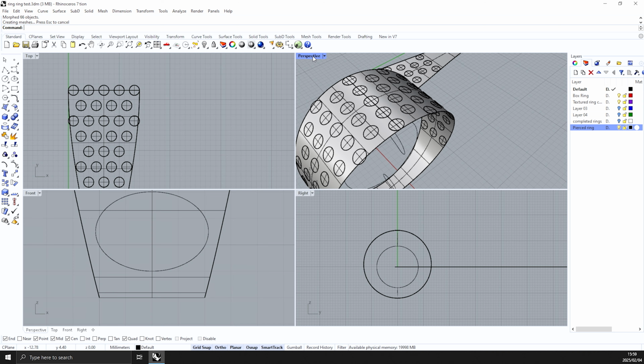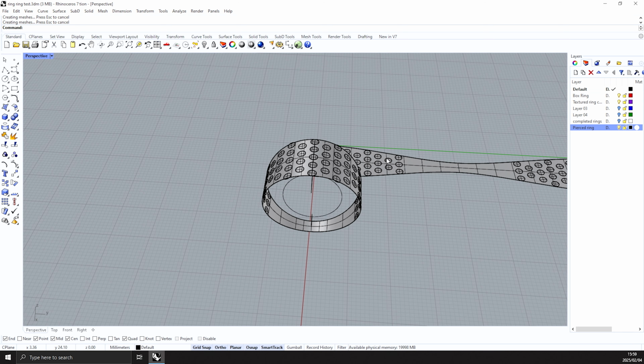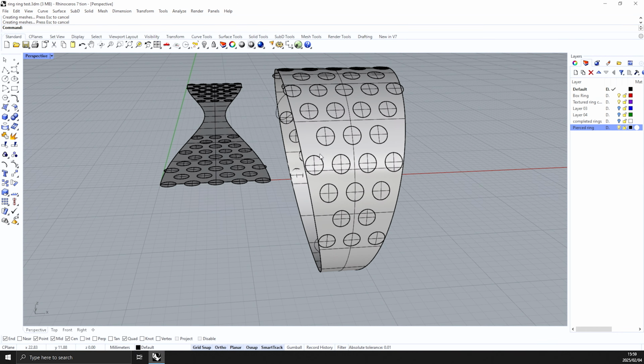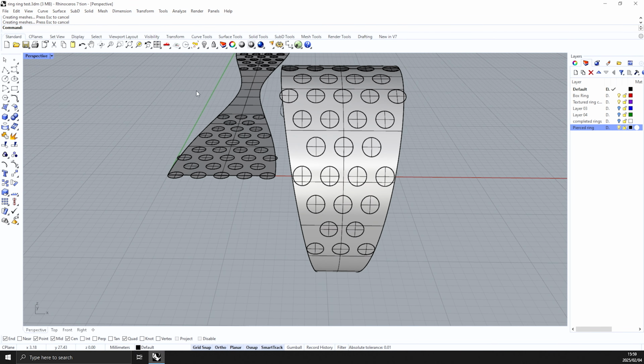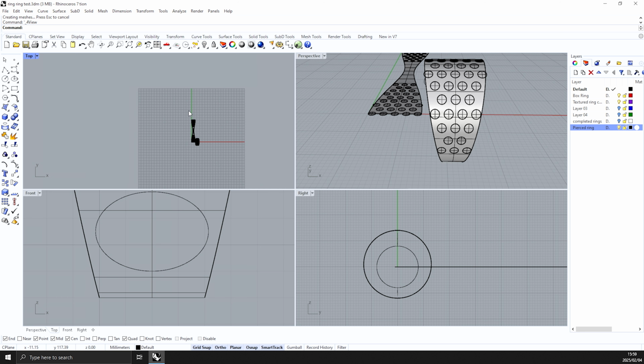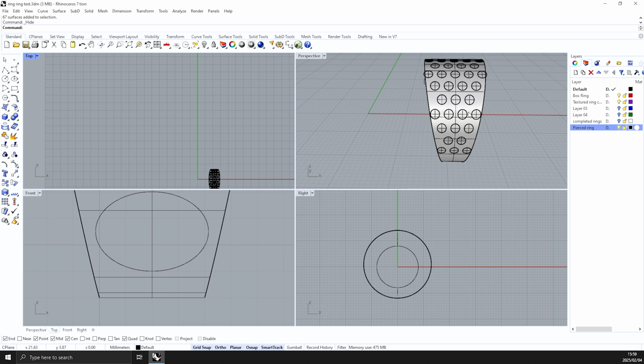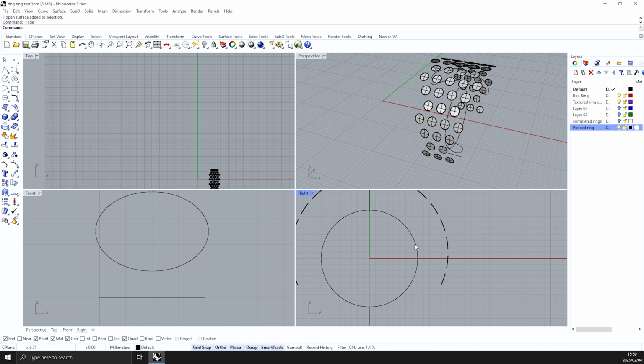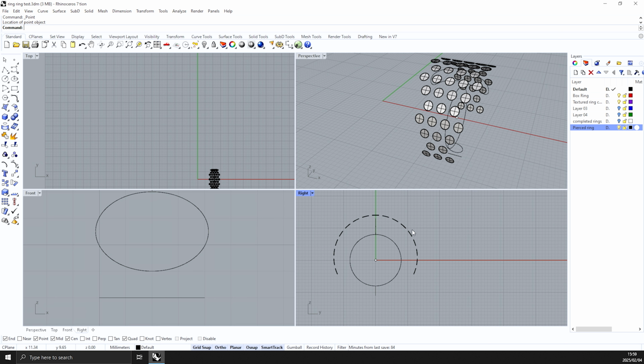And now you can see those shapes have been transposed from that surface over there onto the original curved surface here. Now, I don't need this unrolled section here anymore. Go ahead and hide that. I also don't need that guy anymore. Hide that. But I do need to mark a central point in my main arc because I'm about to use that point to pull these shapes in and create solids.